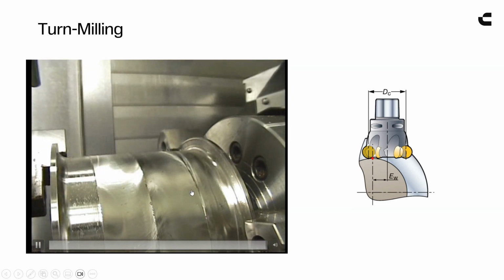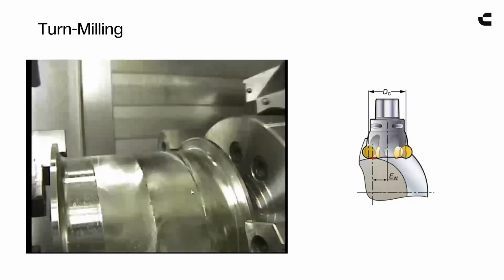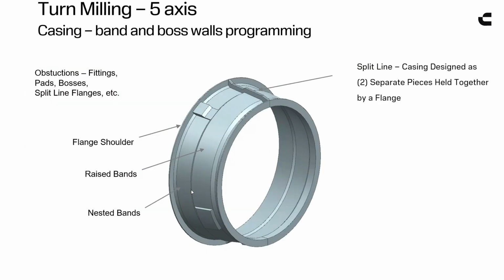We can come back in with a carbide round button cutter, as well as even a shoulder cutter indexable with a wiper. And we can use a wiper insert to give it a fantastic surface finish, to where it holds excellent tolerance and it's hard to even see, without just seeing the cut lines, the difference between the turned area and the milled area. So excellent solution for components that have obstructions in the way that you just can't turn.